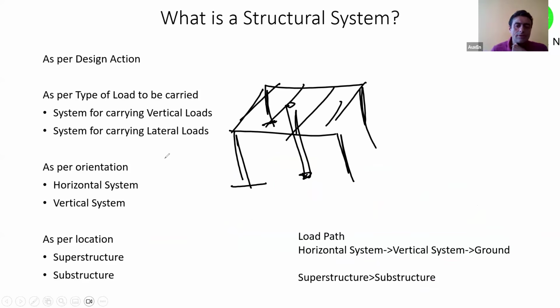That if there is a lateral load, and if there is a failure at the slab to column junction, or even under gravity loads, but more so under lateral loads, if there is a failure at the slab column junction, it will lead to a catastrophic failure, direct failure. So this does not have multiple load paths, let's say. But if I introduce RCC structural walls over here.